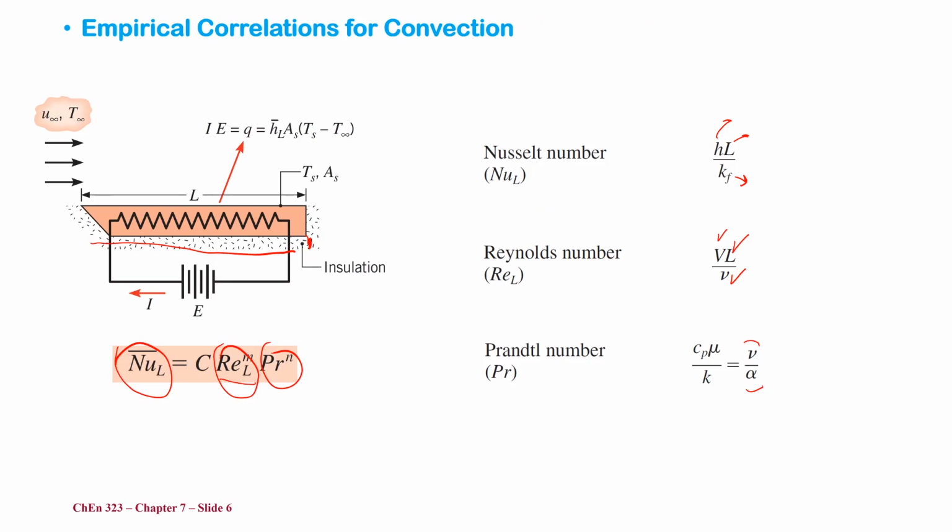So before we move on, just the main idea here. Nusselt number is basically telling us h. So h is a function of velocity, if you want to think about it in simpler terms. Reynolds number contains the velocity, and h is basically what we are trying to calculate, in this case h bar, based on the flow condition.